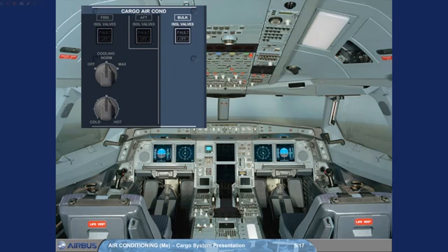The bulk cargo compartment control is located on the right side of the cargo aircon panel, which is on the overhead panel. An ISOL valve push-button switch, which is normally in the lights-out position, can be used to manually control the inlet and outlet isolation valves to close and the extraction fan to stop, or to leave the automatic control of these valves and fan to the ventilation controller.